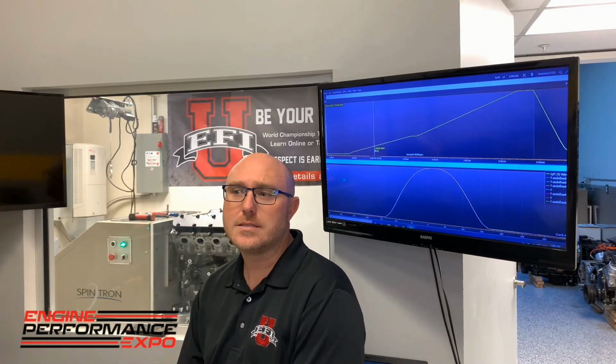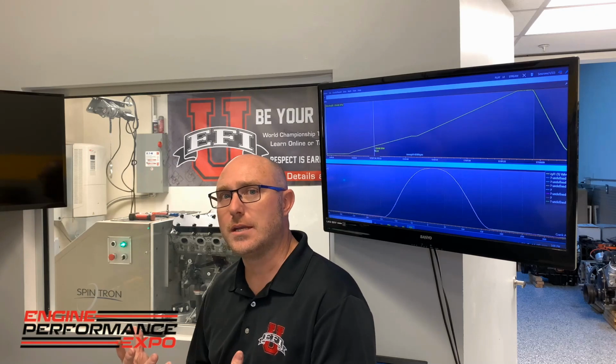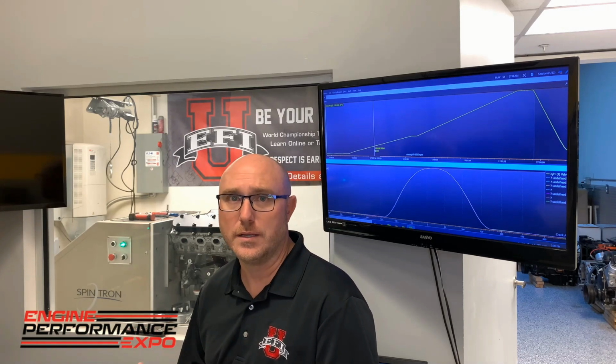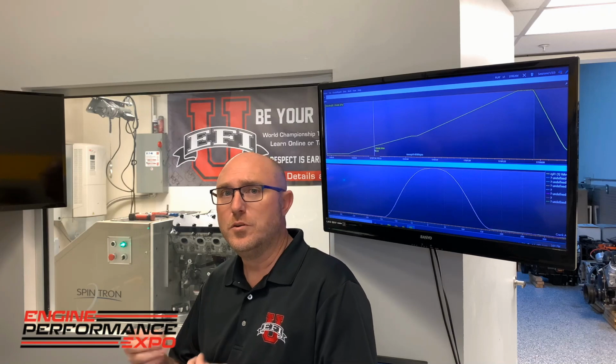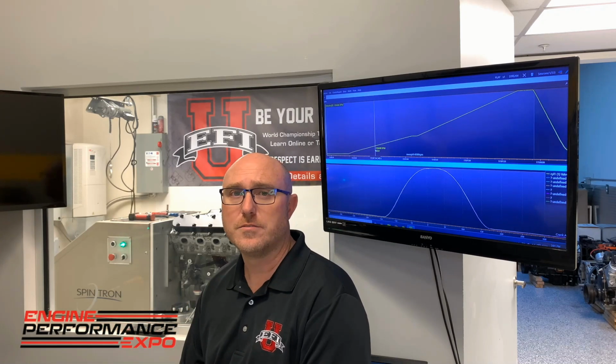The only thing is that when we actually run the engine, it's dynamic and it's variable, and it doesn't stay static like it did on my engine stand. Things bend, things flex. When they flex and bend, they can rebound at a different time. So all throughout the RPM range that you run the engine, this dynamic movement and instability of parts, going in and out of being a stable, good working valve train, actually affects the engine's performance.